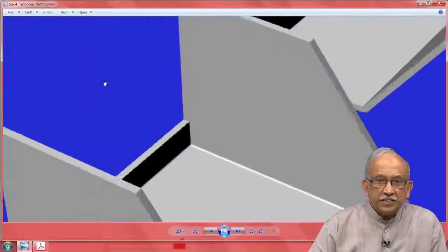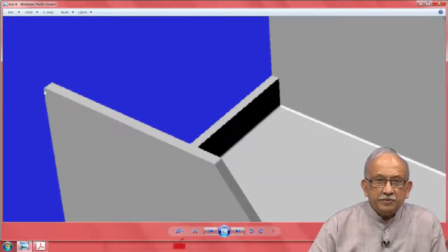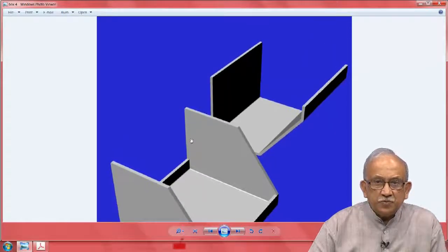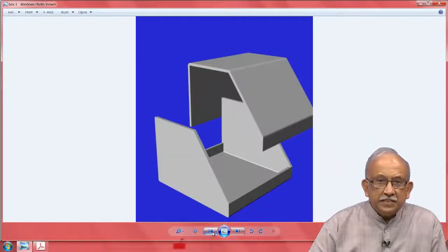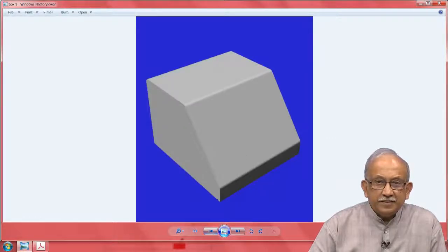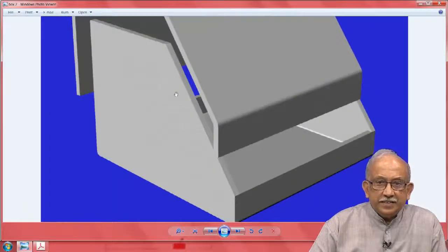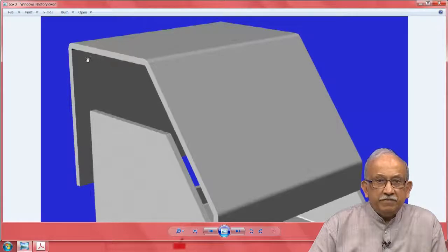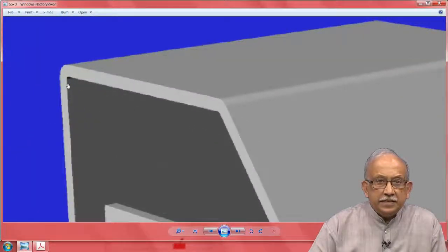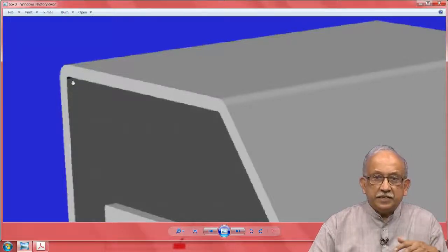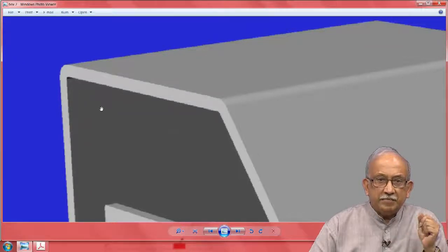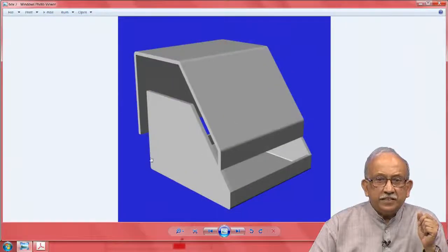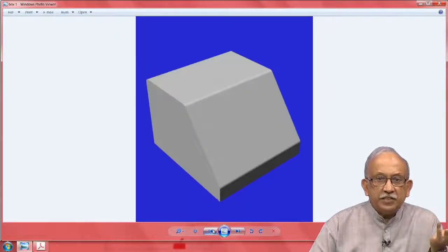Now we will come back to this corner. Have you seen here again there is a bending here which may or may not be required. However, this bend corresponds to this bend here of this top cover. Why is this required? Because after you finish, it should fit neatly one over the other. If you have clarity of your concept, now you see they appear to fit quite close. So in this corner, I have an internal bending radius which depends a little on the machinery and the tools we have, plus something which is related to the external bending, the thickness of the whole thing. Now together, if you place them, they seem to fit nicely, absolutely no issue about it at all. I have a beautiful box here.